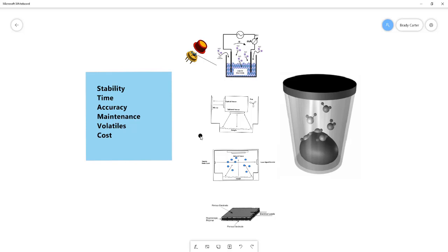The electrical property sensor also is less susceptible to cleanliness issues, but because of its tendency for the polymer's electrical properties to shift and change depending on what's happening, it also needs to be frequently verified and may have to have calibration adjustments as well.